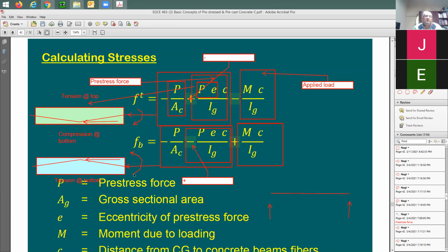Yes, that makes sense. So the only thing that is going to change is the additional moment, or the moment due to the eccentricity. But moment due to load is going to be the same. Axial compressive stress in both top and bottom is going to be the same. Okay. So actually, you're kind of killing the beam here. I mean, here you're resisting the applied load by putting a beam opposite to the applied moment. But here, you're not helping. You're pushing the beam down more.